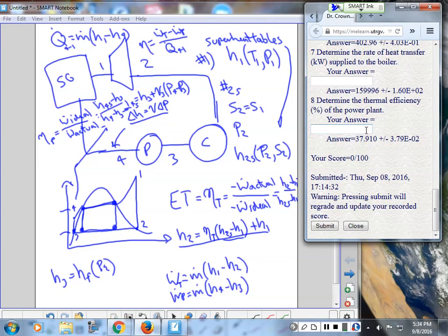So it helps us make a connection between the Rankine and the Carnot. The only problem with this one is this is my maximum temperature, so I need to do a Carnot cycle like that, and that's tough to do with the saturation curve in there. But anyway, the efficiency for the Carnot cycle is always going to give us a limit to any other power cycle. So, the first problem, the Carnot efficiency.